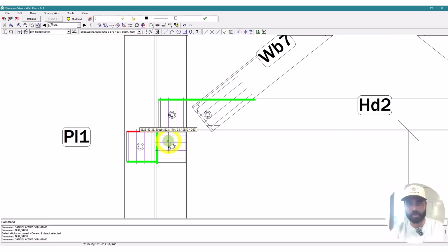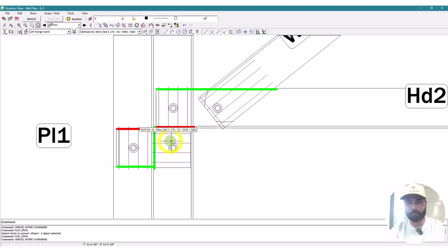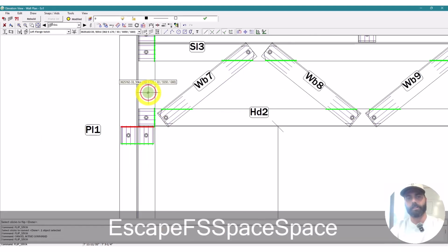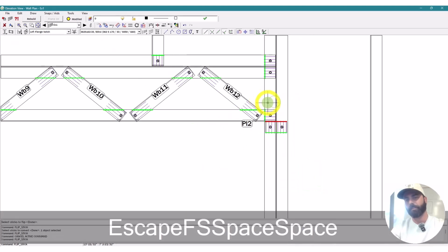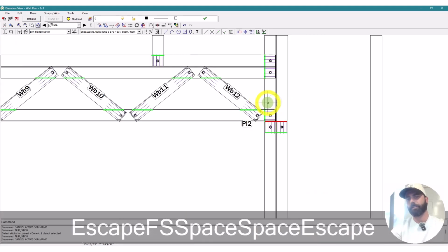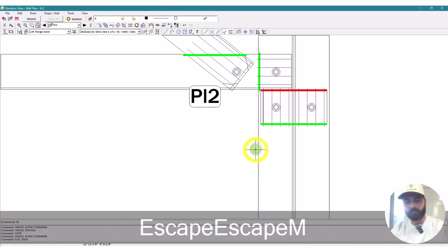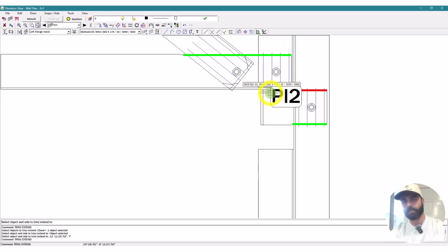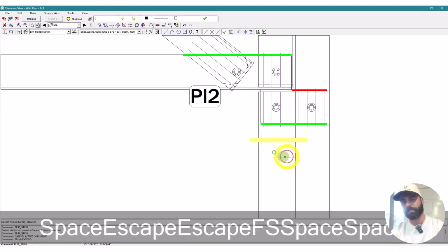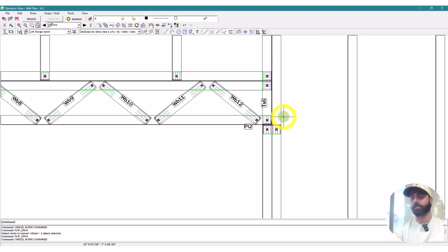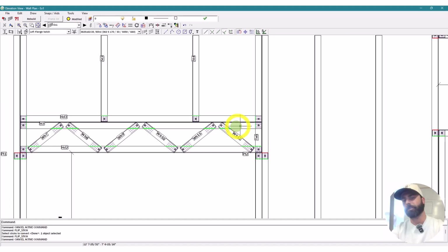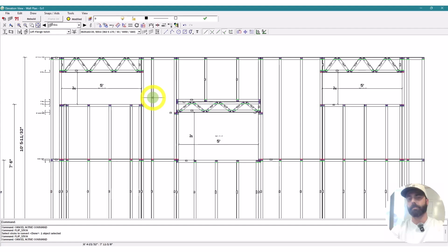So I would go to member break, I'd click that there, I'd pull this one up to here, like that. I'd pull this one to here. This one is the smooth side of your window, and now you have the smooth side screwing into the screws. Both of the webs are touching, so now you could take a drill and drill this header in separately. So if you guys are shipping massive headers, you now have the ability to add a new panel break location. You could do the same thing with the sill. All right, so you could pull this back and turn this into its own panel, right? And then the guys could screw that in on site.